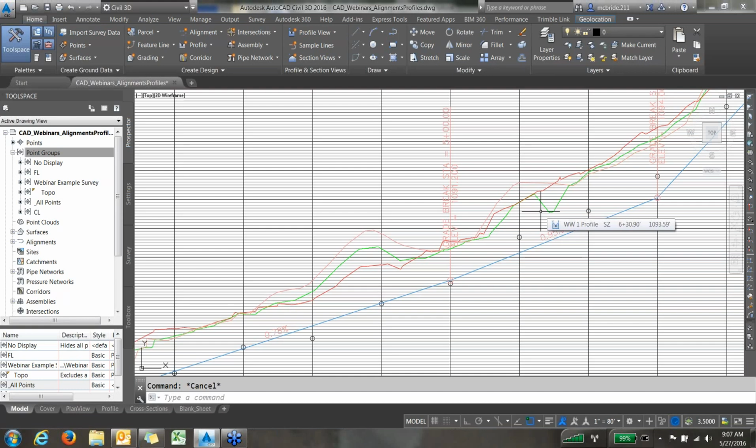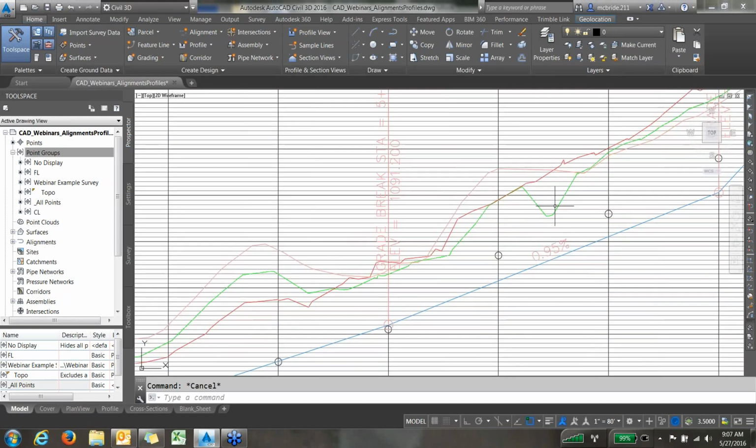If you figure out, based on this situation, that I need a depth of 1.5 instead of 1.2, you're going to have to go through here and see if you have enough depth to cover your 1.5 foot depth. Because if you don't, then the top banks of your grass waterway are going to be above the natural ground line, and you won't be able to get overland flow into your grass waterway.